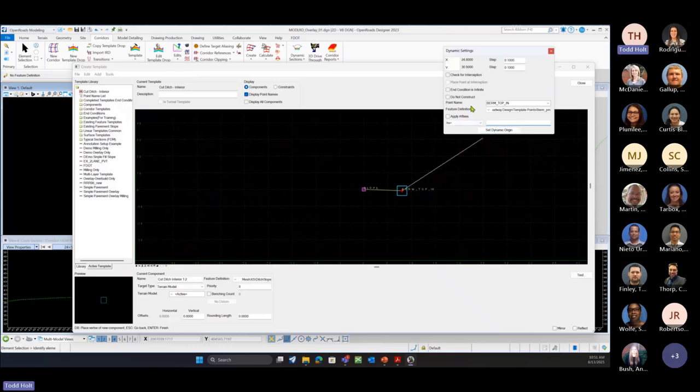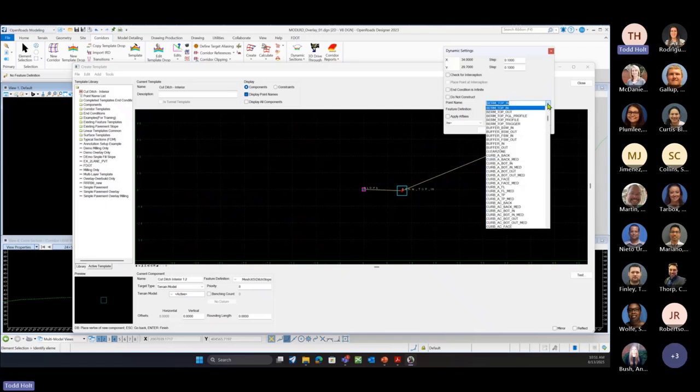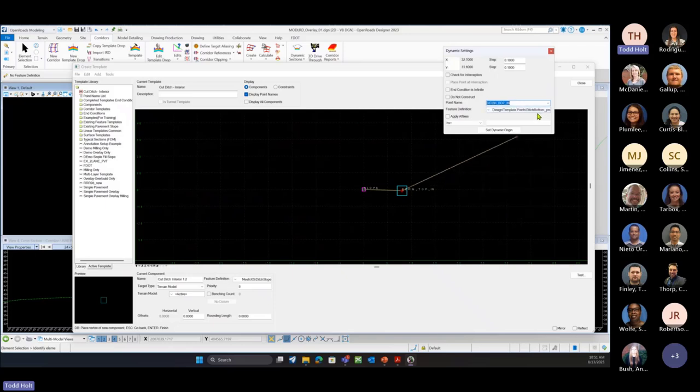Right, so now we're going to draw our ditch bottom, or that back slope. So we're going to find a new point. So maybe in our list we have our ditch points that we can find. So maybe this is our ditch bottom in that we're going to use, right? And again, that's just going to set that feature definition. We're going to use a precision input again as HS. We're going to have this be 6, and then we'll do comma, and this time we want this to be a 1 to 3 slope.